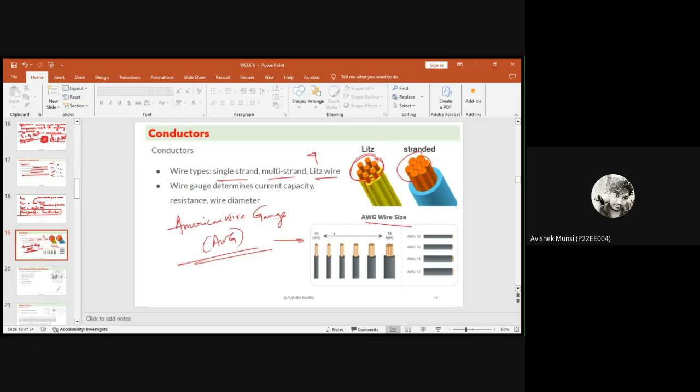It can range from AWG 40 to 18 as we are moving into AWG 12. So it will be wider and thicker compared to the higher values. Keep in mind how much current it draws, and based on that you have to decide how much AWG wire you are choosing for your inductor.